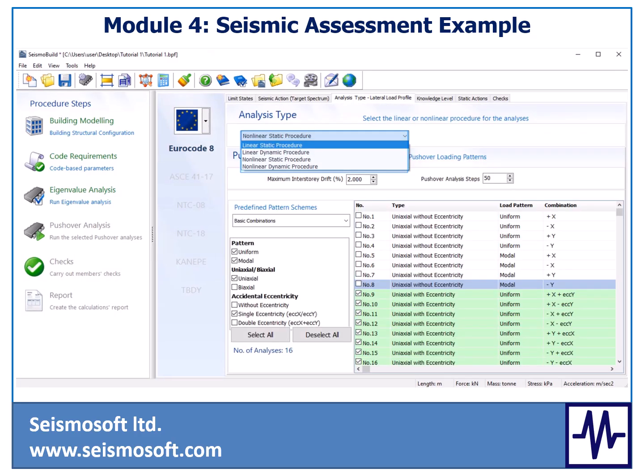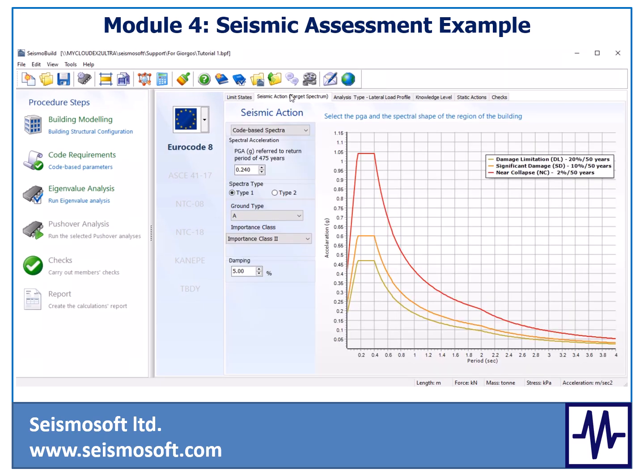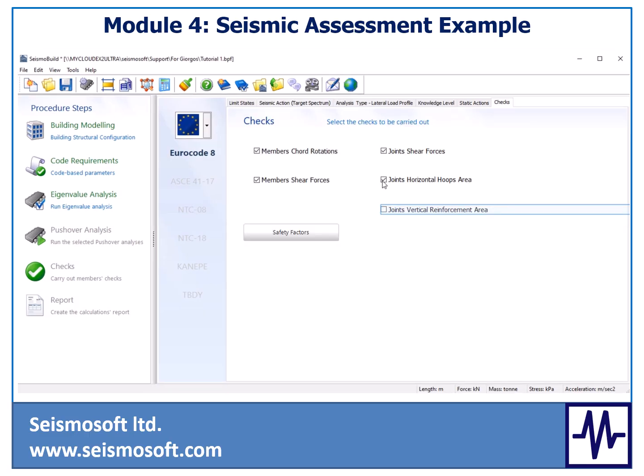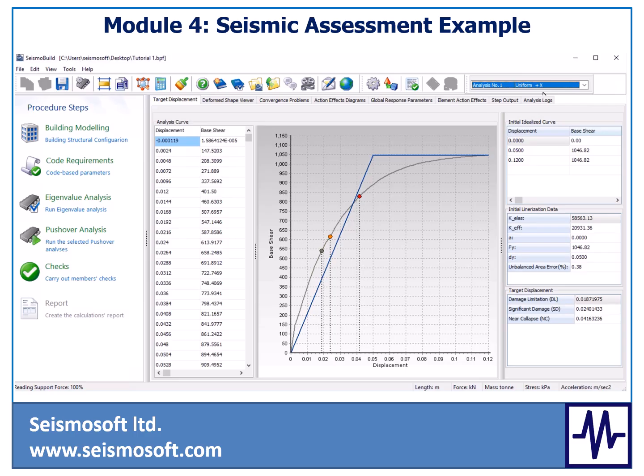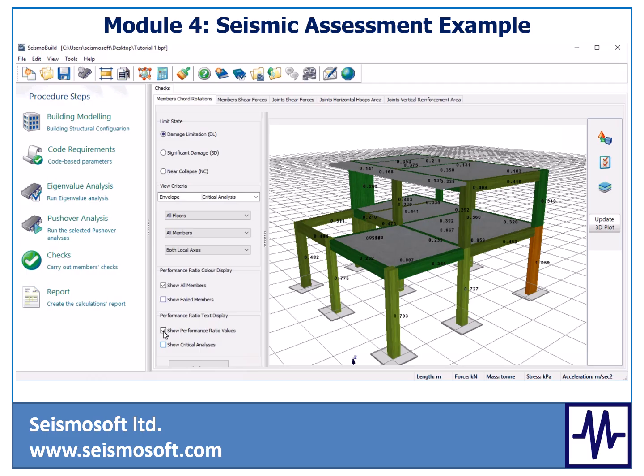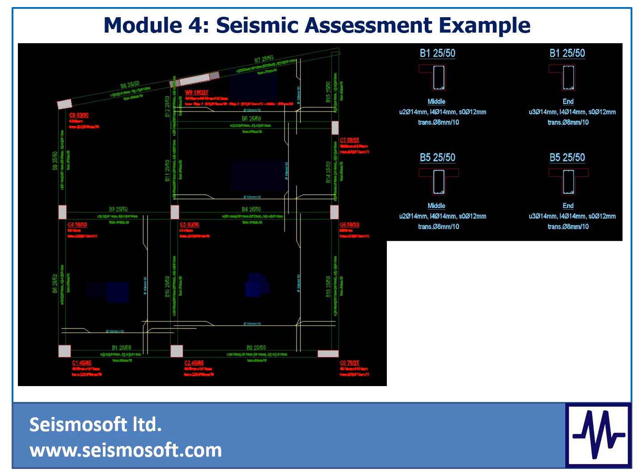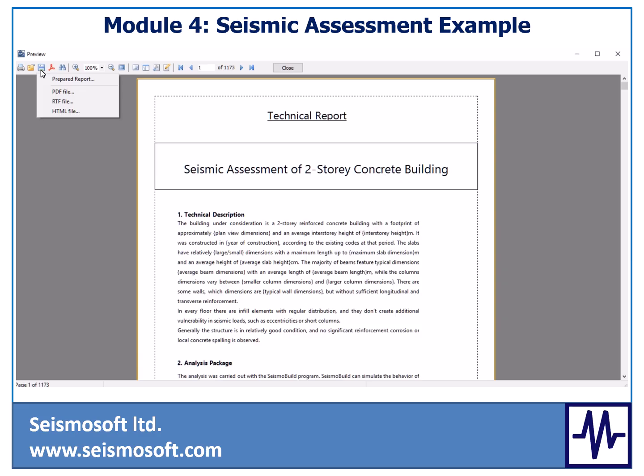The methods of analysis and the loading patterns. The seismic action. And the checks to be performed. Then an eigenvalue analysis will be carried out, together with the necessary pushover analyses. Finally, the results from the checks will be obtained. The CAD drawings will be exported, and the technical report with all the checks will be created.